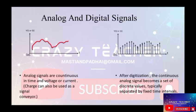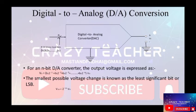Ultimately, for digital signals, we need to store the values of the signals at these discrete points only. If you want a good approximation of the analog signal, then you have to sample at a much higher rate, and if not, you can sample at a lower rate. From communication theory, you can find out the minimum rate at which we have to do the sampling for periodic signals, for reconstruction purposes.